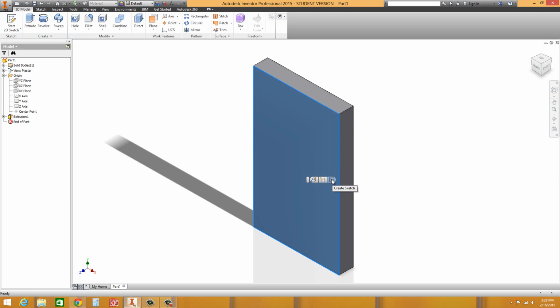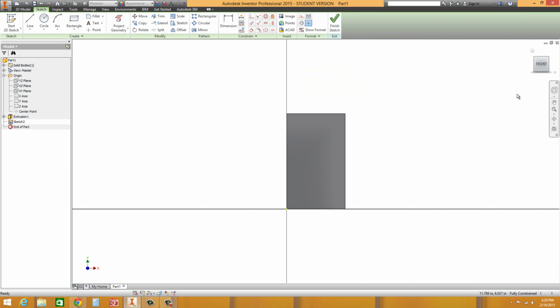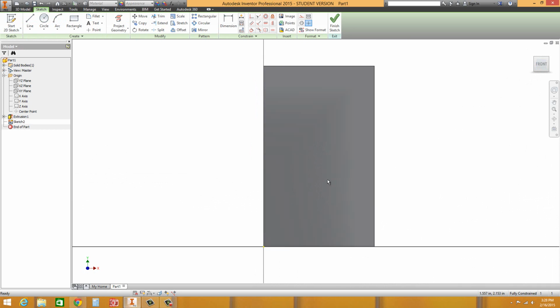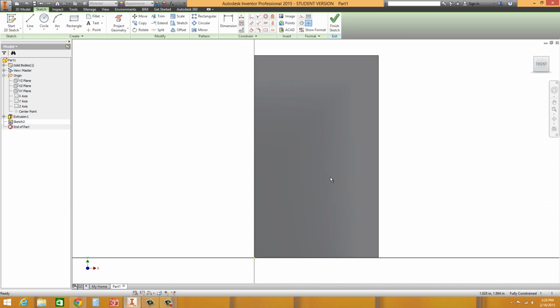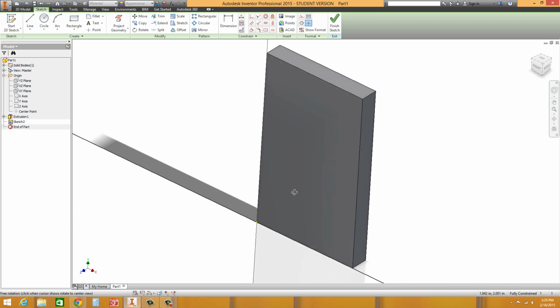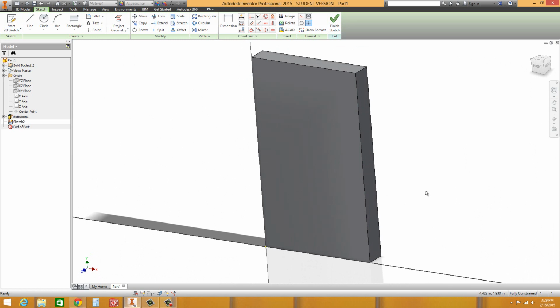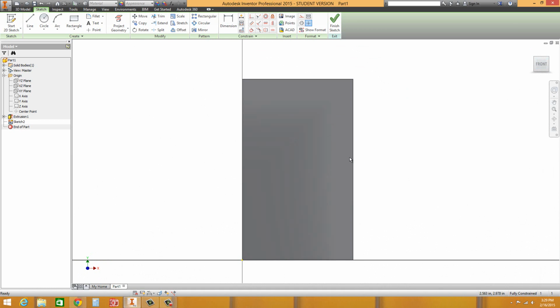So I'm going to use the quick launch here, Create Sketch. And again, I'm going to click on the front box just to make it zoom to fit here. Now notice you could scroll in and out with your scroll button on your mouse. If you hold the Shift key, by the way, and your middle mouse button, which is the scroll, and move your mouse left and right, up and down, you can actually dynamically rotate your model in 3D space. Release both of them, and then just go back to the front view orientation box. I would recommend practicing that for a little bit.